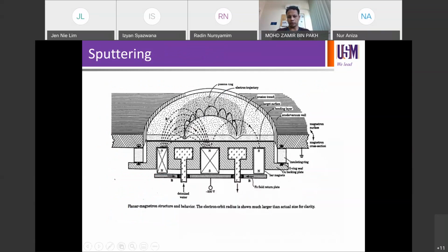The magnet is here at the back. On this front side, the eroded part is the target material. So this is all your target material, for example, ITO. That's the eroded part there, the center, due to the concentration of the deposition over there, which indicates the presence of a magnetic field around the areas.